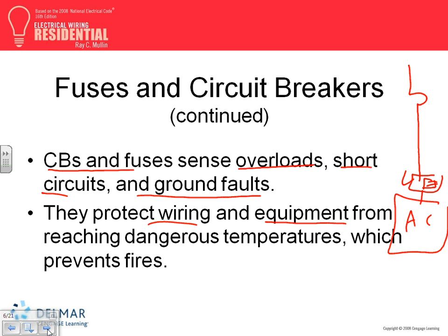In these scenarios, first of all, you have a circuit breaker here. This circuit breaker is to protect the cable. And then the manufacturers say, who the heck are you to size an overcurrent protection device to protect my equipment? I have my own engineers in-house that can design a specifically designed fuse that can protect my equipment, and I care less about your overcurrent protection device ahead of me. A lot of manufacturers, guys, protect their equipment. So what do they do? They have a tiny little beautiful fuse, properly sized and designed, type-wise and size-wise, and they stick it right ahead of the equipment, and this fuse will protect the equipment.